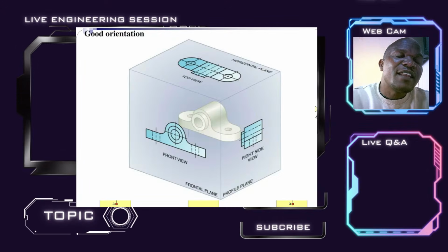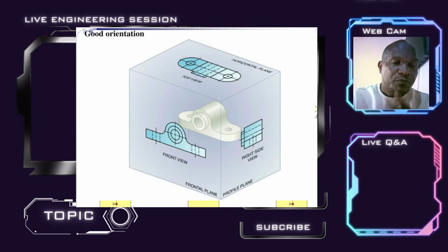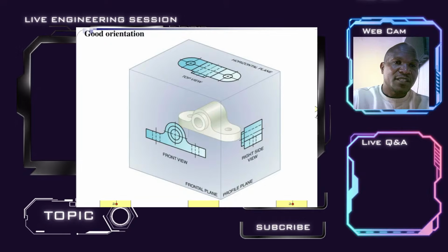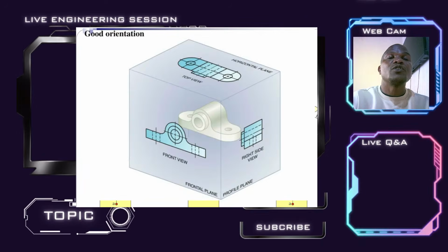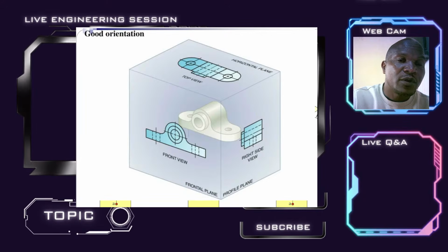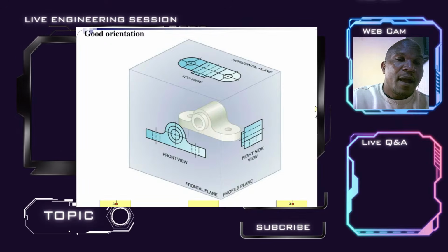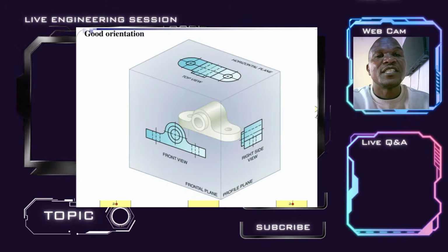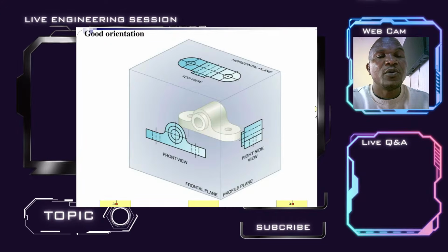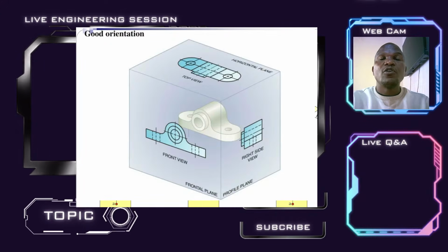In the hidden lines, the features of both holes are visible in the front view. Therefore, easily someone will tell that voila, there is a hidden feature on this side or on this side of the block, and I need to move myself in order to view it. And if you go to the top, you'll see that they were really holes. But from the front view, you'll be able to see the through hole. That one is very well communicated from the side view, the hidden lines. We will also discuss how those are obtained.